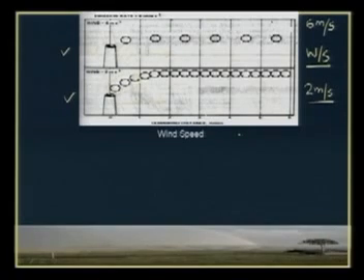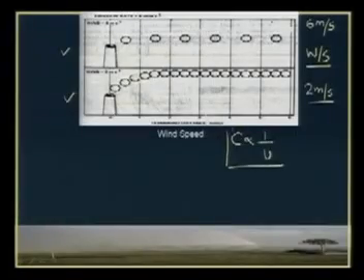So normally we consider the concentration of the pollutant to be inversely proportional to the wind speed. That's a very important concept, and we'll use it later in our succeeding lectures. So this is very important: speed can directly cause a decrease in the concentration. And wind direction we have already seen; we know which location the pollutants will have an impact on. With this concept, there is another concept which we want to discuss, which is the calm conditions.